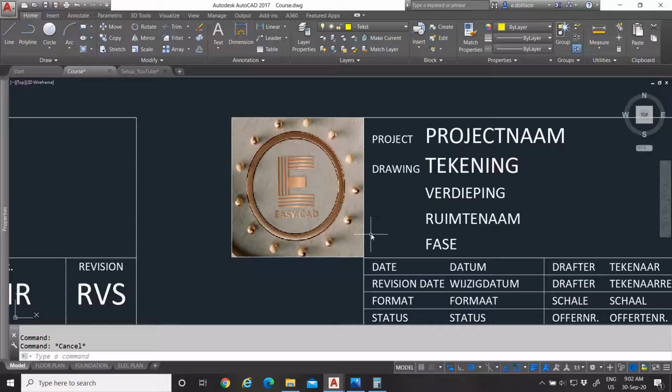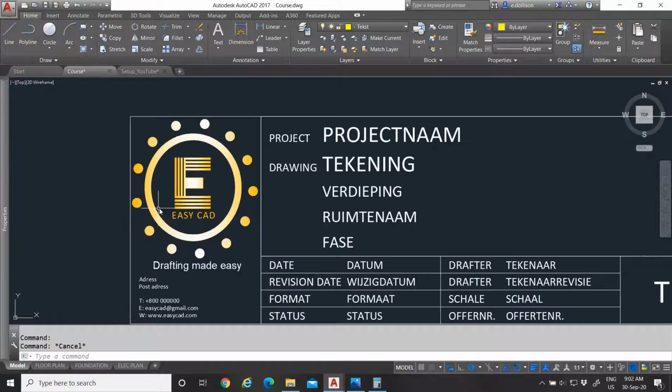So even though your drawing is the same, it will be printed differently in every printer because images, depending on the quality of your printer, affect how your logo looks on your drawing. Whereas if you draw it yourself with standard geometry within AutoCAD, then you'll be sure that your logo on your drawing would always look the same no matter what printer you print it on, generally, because I must say some printers have really bad quality.